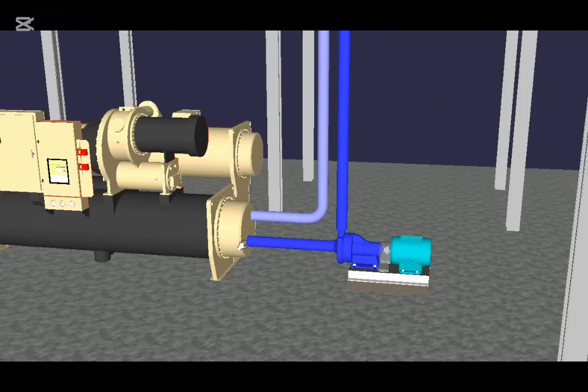And you'll notice that I've colored these pipes in. One is the dark blue, that's for leaving the evaporator, and I put it at dark blue so that you know that it is a much cooler temperature. So this is leaving at about 8 degrees, maybe 6 to 8 degrees, and is leaving in this design at 54 liters per second.